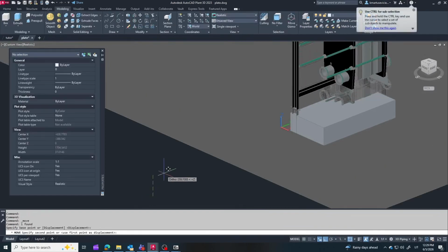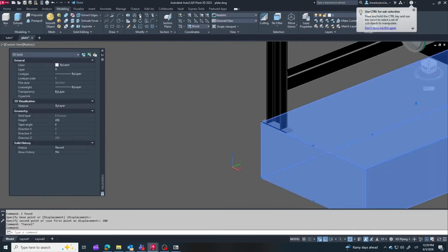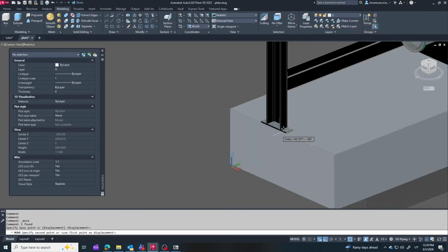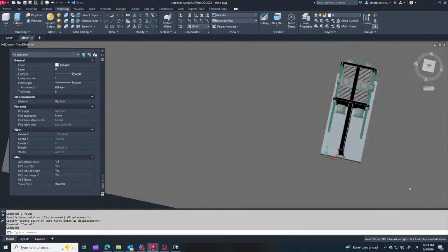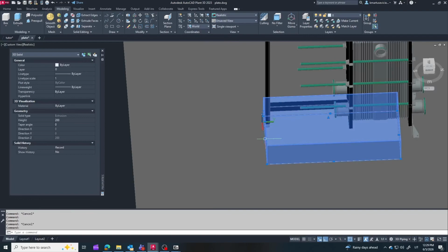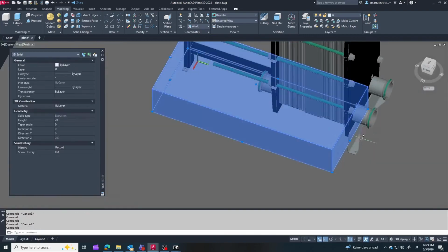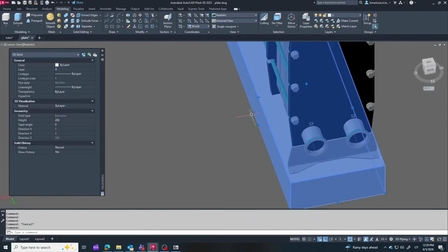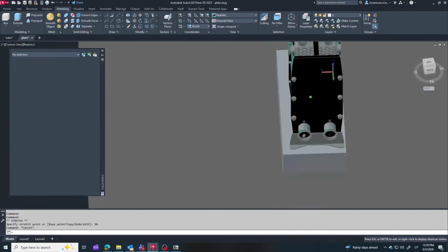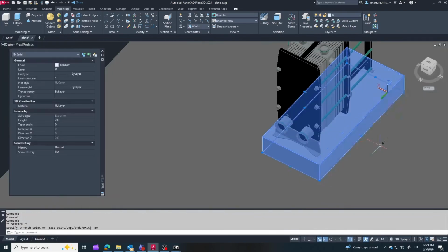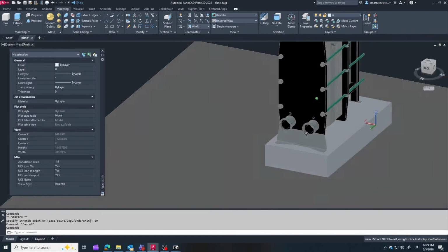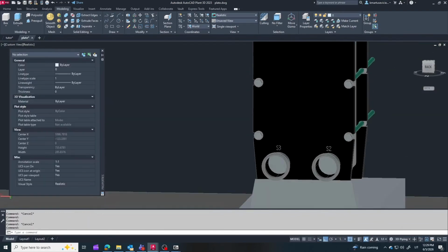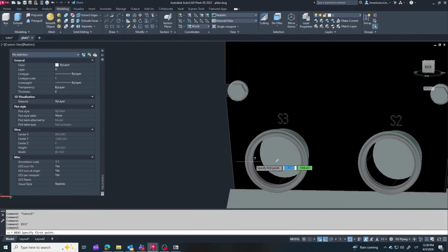I just drew a generic box and stretched it to size. However, when designing foundations, always keep your dimensions precise. In this case, 1000 by 500 by 200 millimeters. Here is a critical tip from real-world projects. Always double-check your inlet and outlet nozzle locations, as well as the hot and cold fluid sides. It's a lifesaver to clearly mark the hot and cold sides directly on your 3D model, so you always know exactly where the flows enter and exit.